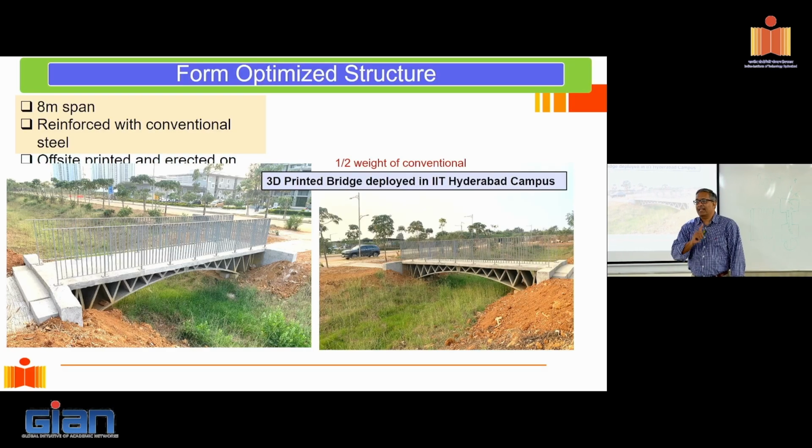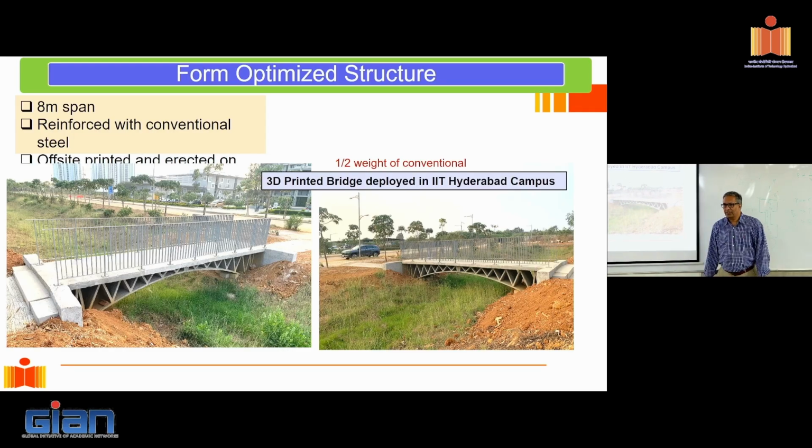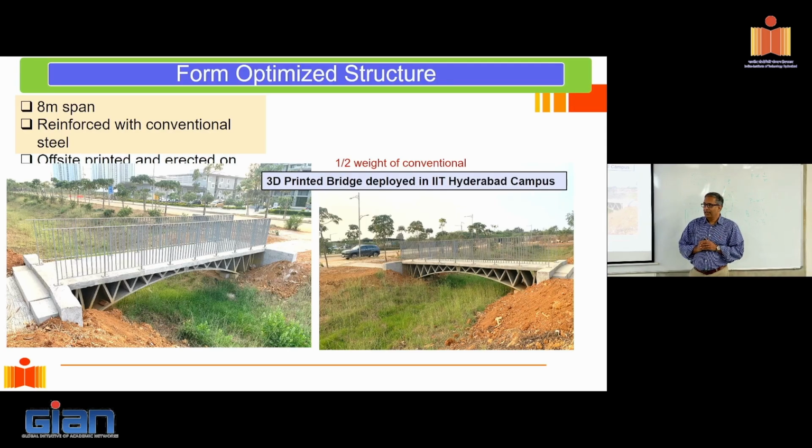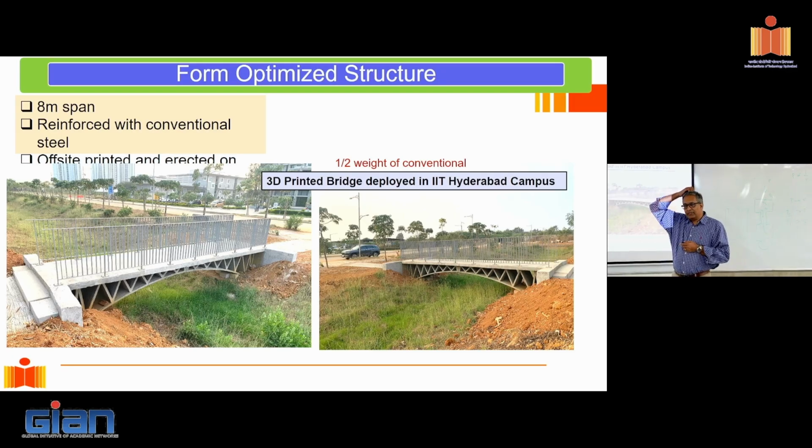You have to address that big problem of cement content. So unless we are addressing that, right, this technology will not truly be sustainable. That is, if you use carbon as your benchmark, as your tag for evaluation, right? Now, we've done that analysis also, and we are finding that if we get to something like, let's say, 600 kgs per cubic meter, so you drop it from 800, 900 kgs per cubic meter to 600, then you have tremendous savings in the carbon tag.